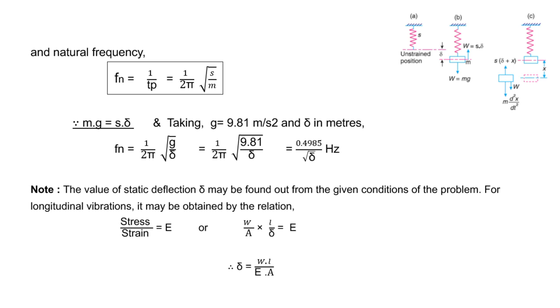Remember this. Now we will simplify the same formula a little bit furthermore. In some problems this simplification is required, so we will simplify it. Since now in this diagram observe W is equal to delta into S, whereas W is equal to mg as well. Therefore spring force and this weight are equal in diagram B. Mg is equal to S into delta.